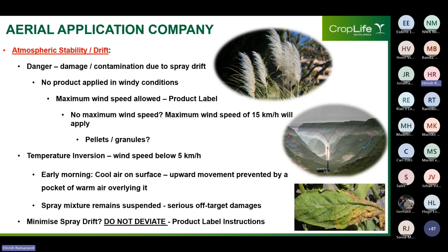During aerial application of crop protection products, drift onto persons, animals, adjacent lands, public roads, footpaths, water supplies, and crops, particularly onto sensitive crops, when non-selective herbicides are being sprayed or when harvesting is taking place, must be avoided. Spray drift has to be minimized by selecting the correct type of formulation and adjuvant and taking into account droplet size, nozzle location, flying height, wind speed and direction, air turbulence and thermal currents, humidity, and temperature. Again, all of which must not deviate from product label instructions.